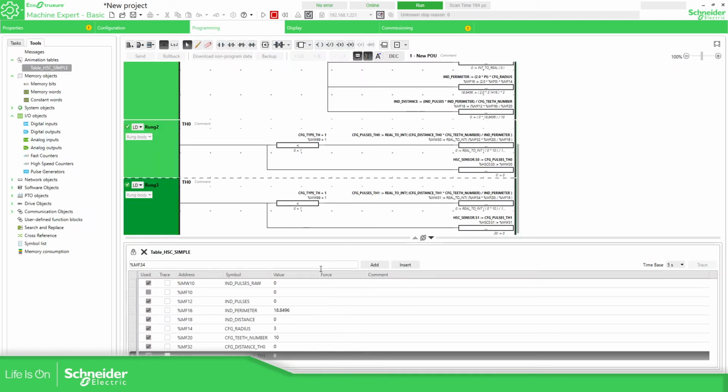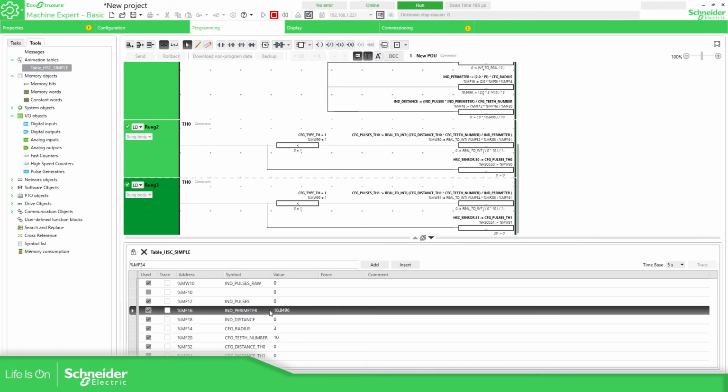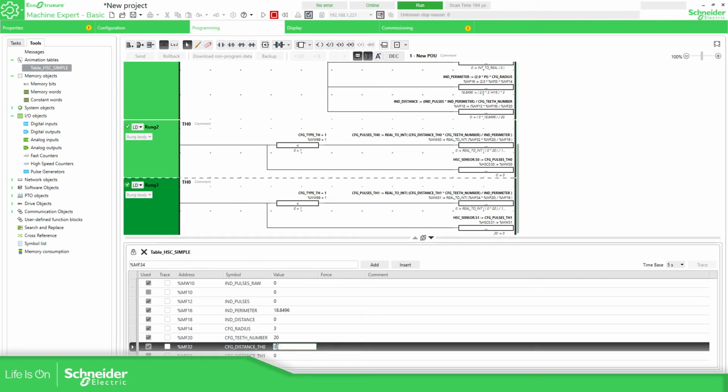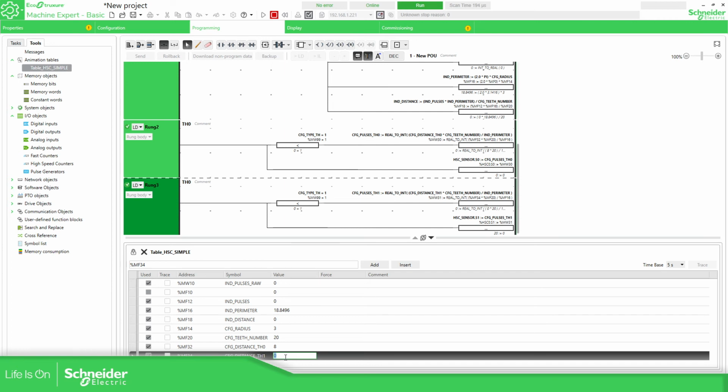So what we need to do now is to configure the threshold. Imagine this one should be when I have the 10, let's configure that I have this distance when I have the 20 now. The first threshold will be at 8 centimeters, and this one will be when I have 15 centimeters, so we're almost to the 20.